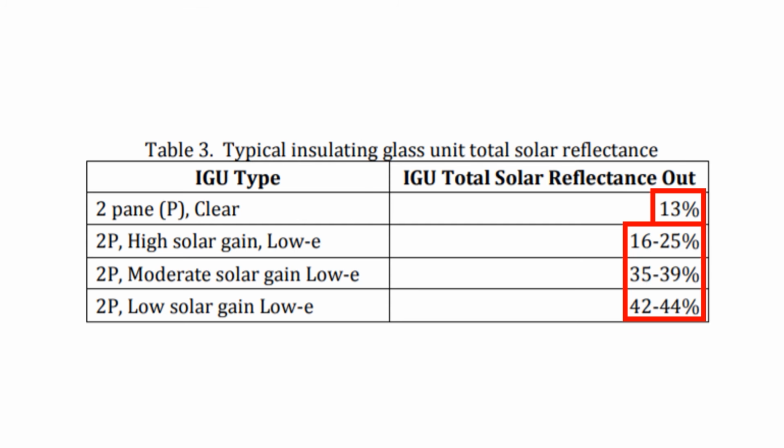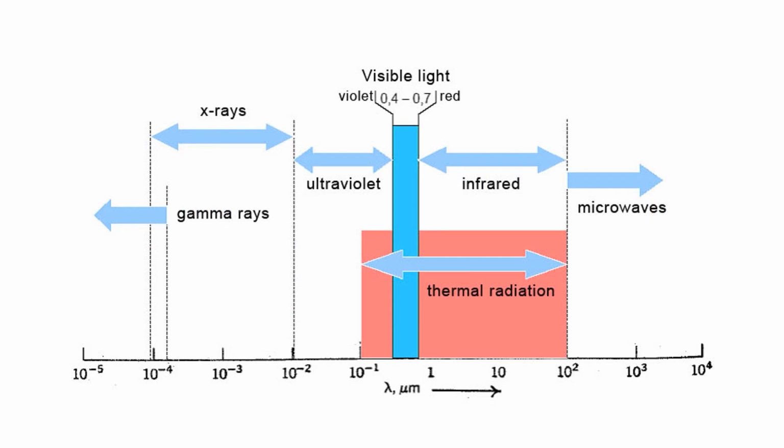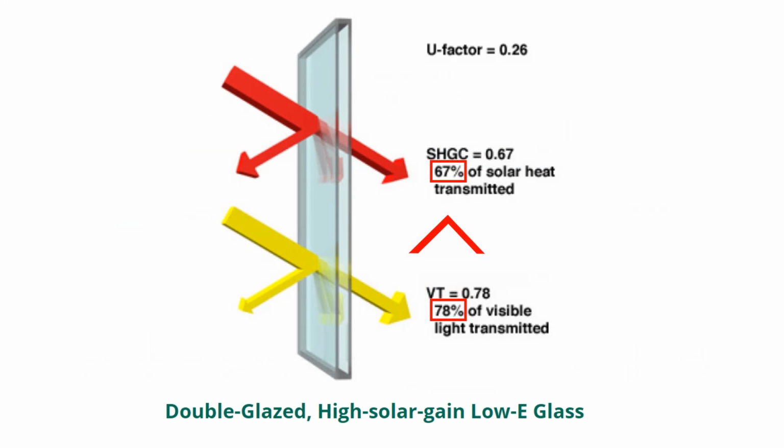For the increased solar reflection, low E coating was used to double glass unit. Low E, low emission, means the insulation of infrared, which is main factor of radiation heat. The low E coated glass has less reflection of visible light compared to solar heat. Therefore, there is no significant problem with transparency while reducing radiation energy.